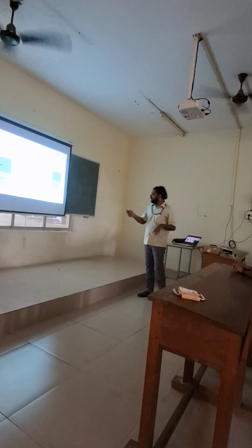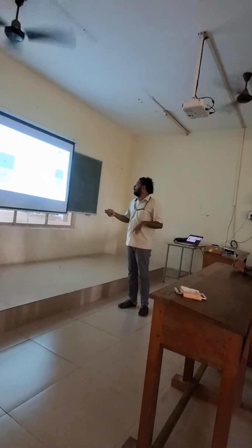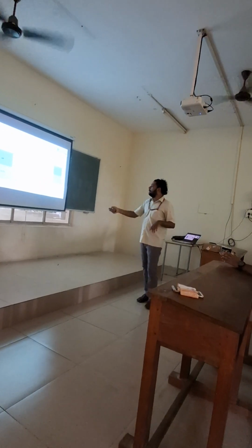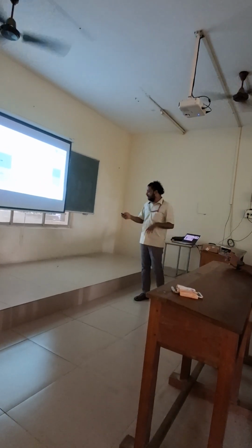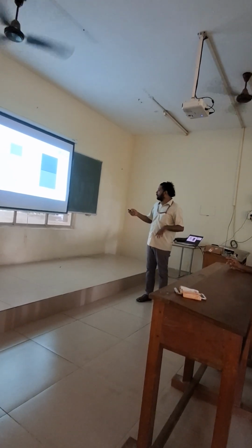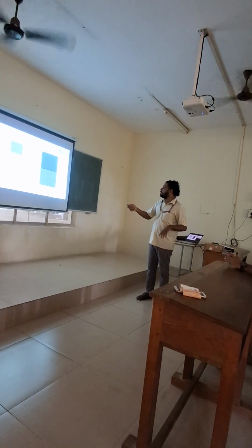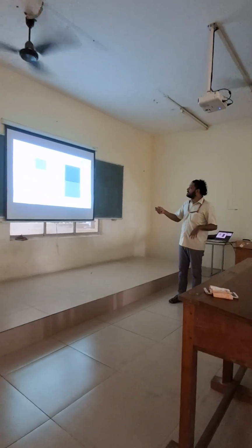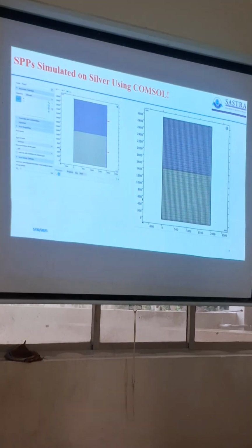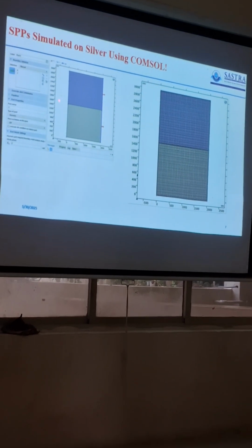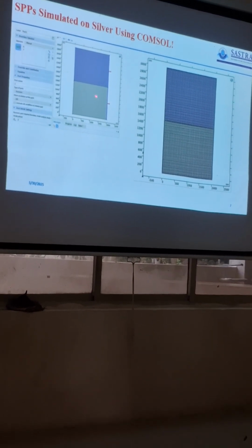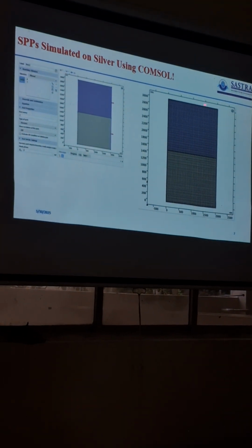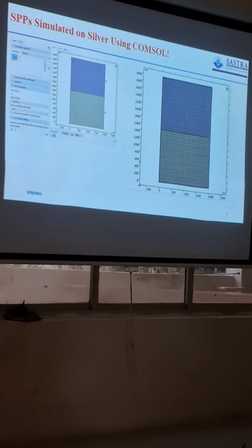So this is a simulation that we did in COMSOL. We have a silver layer, and I'm going to initialize all the material parameters at the beginning. I'm going to initialize this particular side of the device as the input port and this side as the output port, meaning that the electromagnetic radiation comes from here to here, has an interaction on the surface, and leaves from the other surface. So this is what the mesh looks like, the rudimentary mesh.